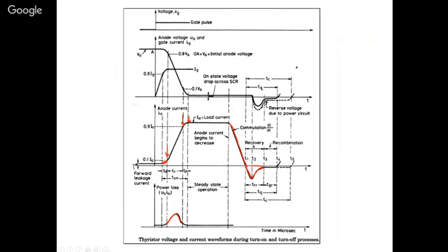So what happens when it is flushed out at a higher rate? There is a dip in voltage here, a high negative voltage is applied here. This negative voltage also depends on the inductor present in the circuit. If the inductance value is more, then this voltage drop will also be more. That may damage our device.